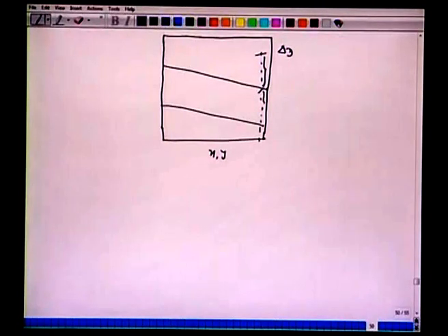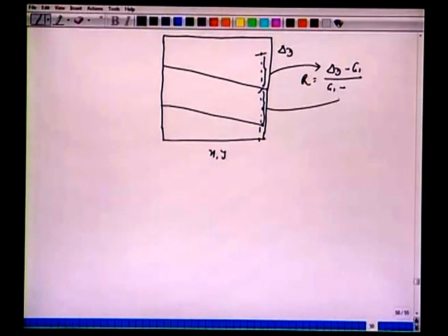That means this ratio R is del D minus G1 over G1 minus D, this segment and this segment. So let's say this is your D here. This is xt, maybe this top product is cold, so it does not necessarily have to lie on here. The enthalpy is given here, we know the reflux ratio. So we can take the two segments, one segment here, one segment here, we can mark this del D point.